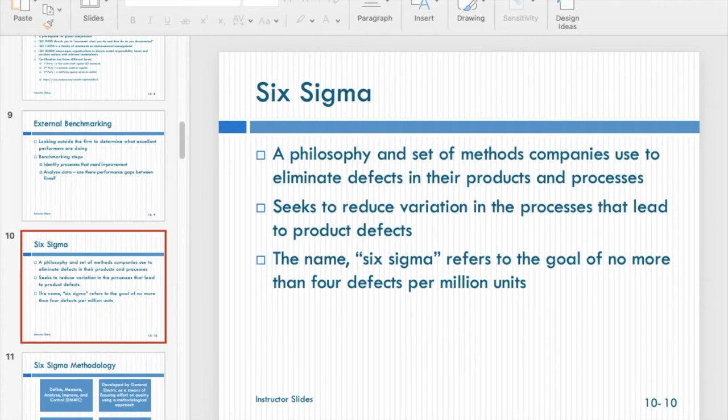So if we have a center point in the middle, there should be 3 sigma at the left-hand side of the central point and 3 sigma at the right-hand side of the central point. That of course is 6 sigma. But in total, if the range designed by management can include 6 sigma for this real production process, normally we say the quality of this product is good enough.